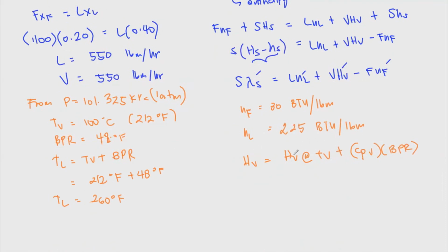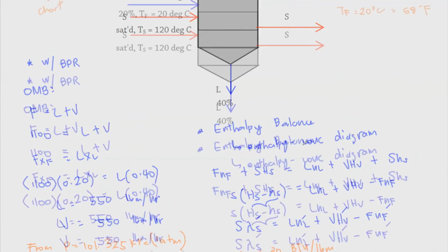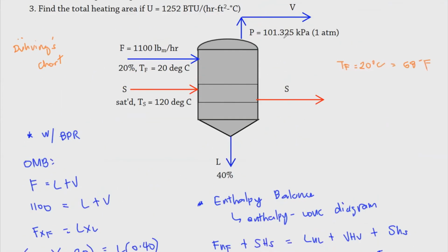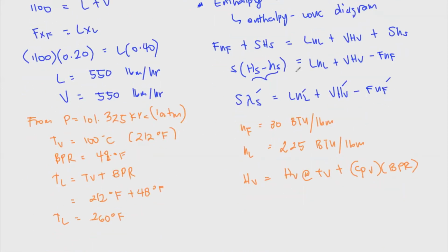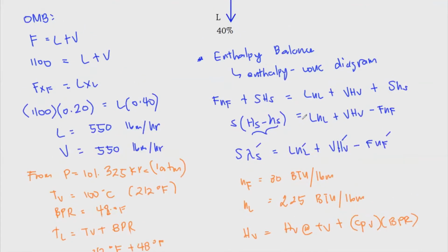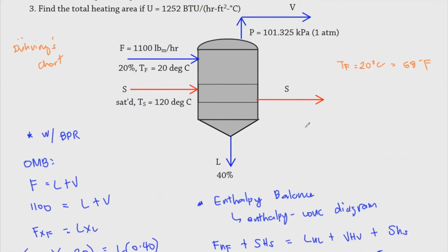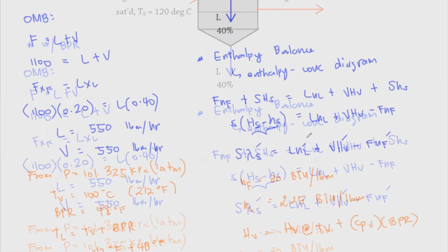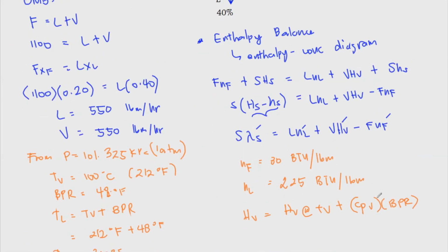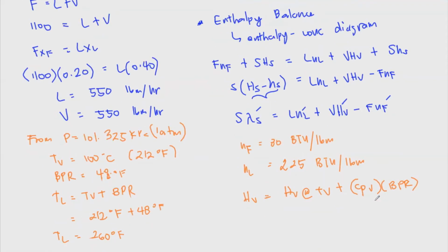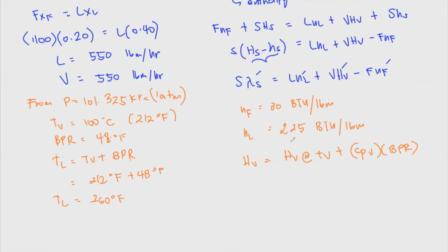That's why if we would account the enthalpy at the moment when the temperature is reaching this operating pressure, the vapor should have been escaping. So that's the enthalpy of that vapor. But because it increases further at that pressure, that's the operating pressure, we should be accounting that sensible heat at the moment when we reach the final solution temperature. So I hope I made it clear on that note.